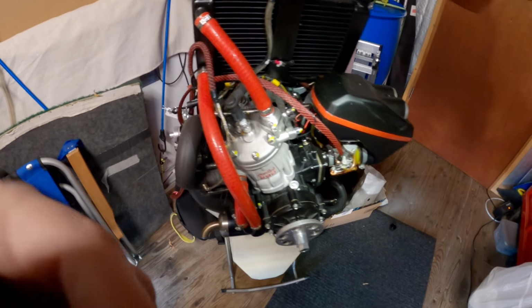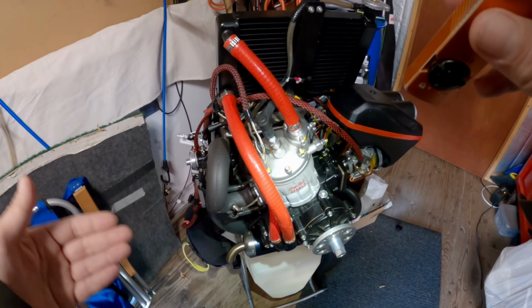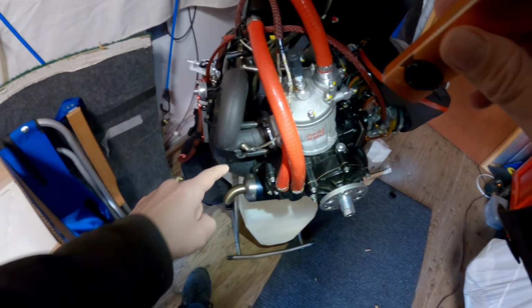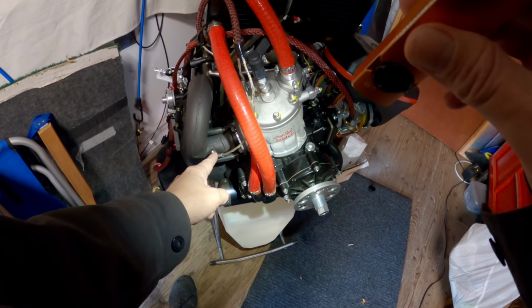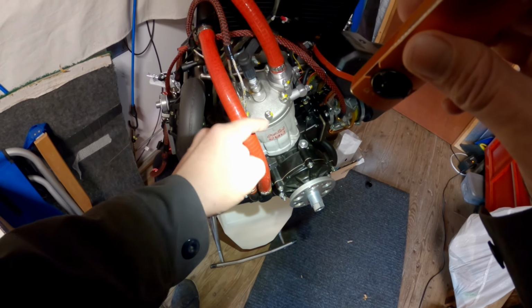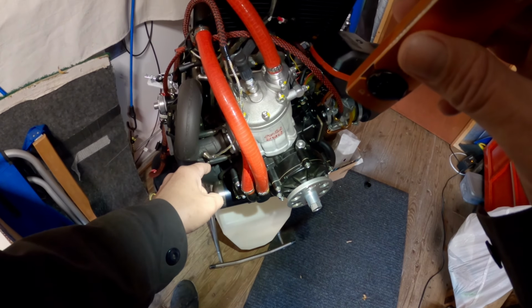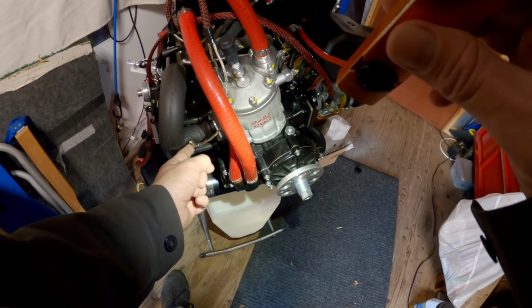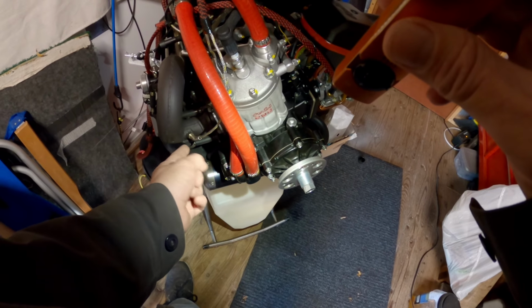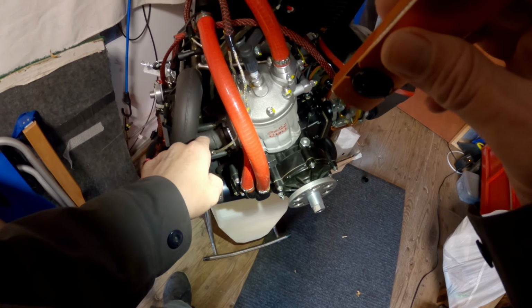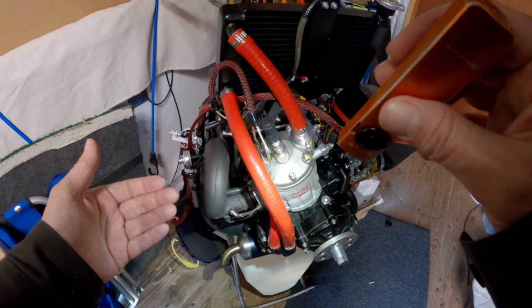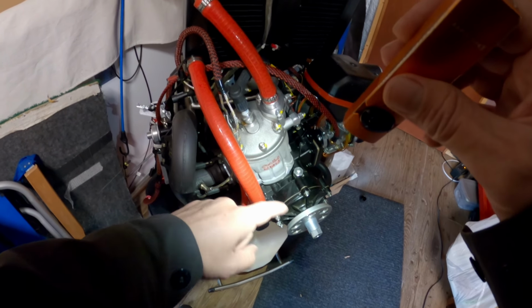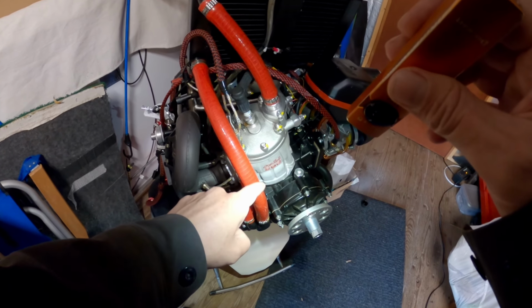So if we come over here to my test bed, where I basically learned how to tune slide carbs with this motor. From the factory, we have an EGT sensor. The great thing about the Polini and the EGT with this engine is that they have a standardized location and a standardized sensor: the probe make and model, the probe depth, and the location of the probe. The advantage of that is we can do apples to apples comparisons with other Polini Thor 202. It does not include any other engine other than the 202.